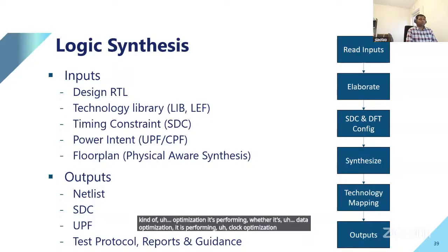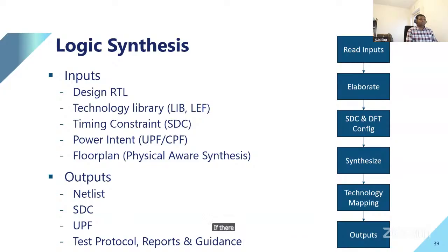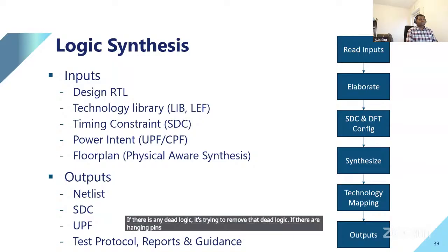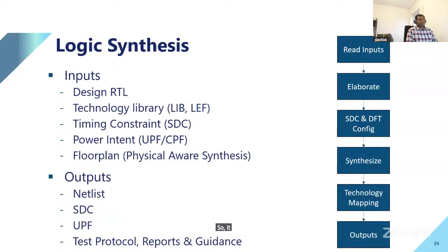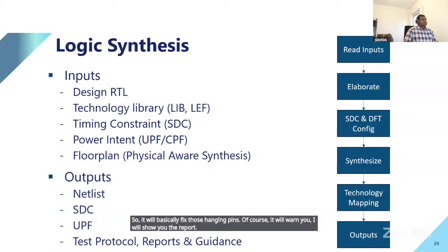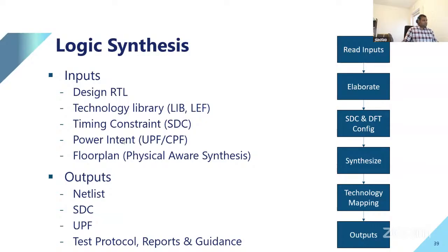If there is any dead logic, it tries to remove that dead logic. If there are hanging pins inside your design which are not used, it will fix those hanging pins. Of course, it will warn you. I will show you the report.